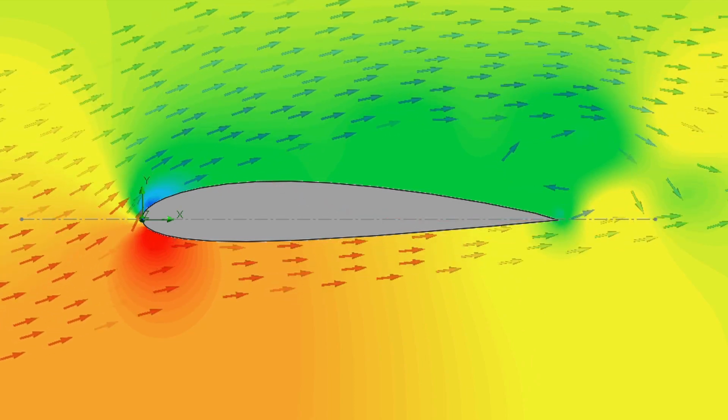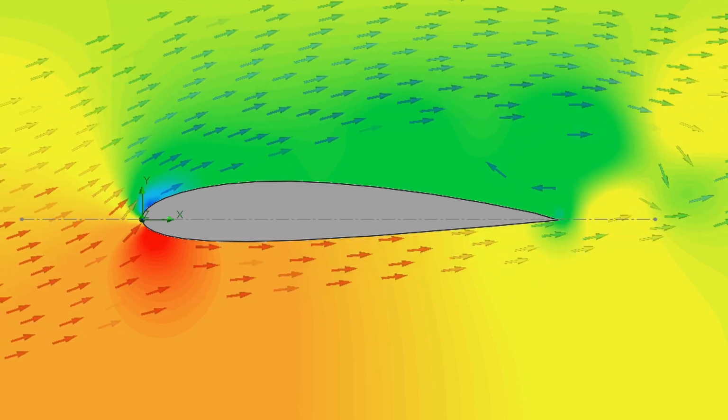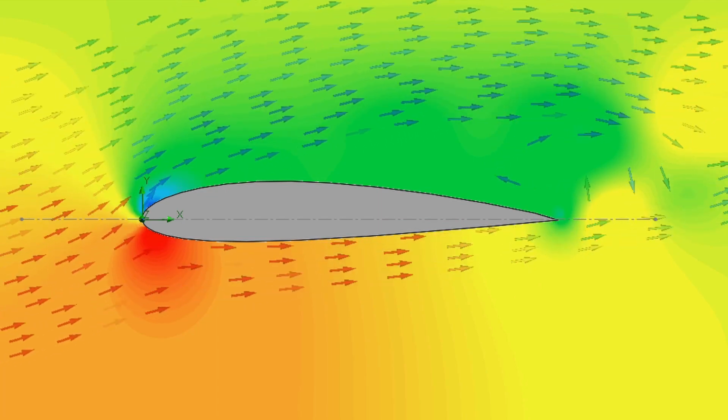Another disadvantage of a higher angle of attack can be found by analyzing the 3D behavior of the airfoil. The difference in pressure near the wing tip forces the air below the wing to the upper part, creating huge vortices causing a lot of induced drag. Obviously, the engineers have found a solution to block this process. It consists in using winglets, which are devices that you always see at the end of the wing.